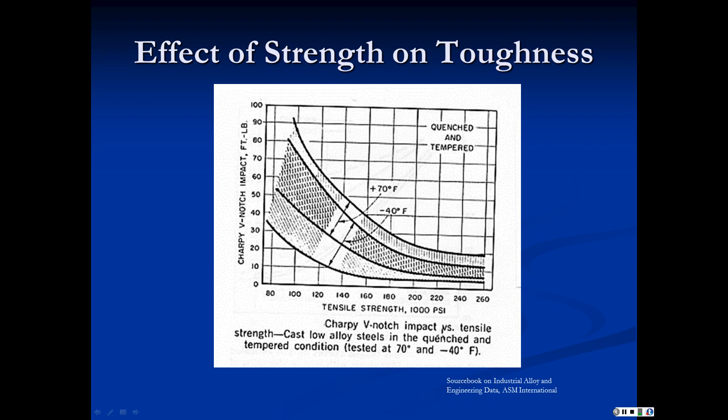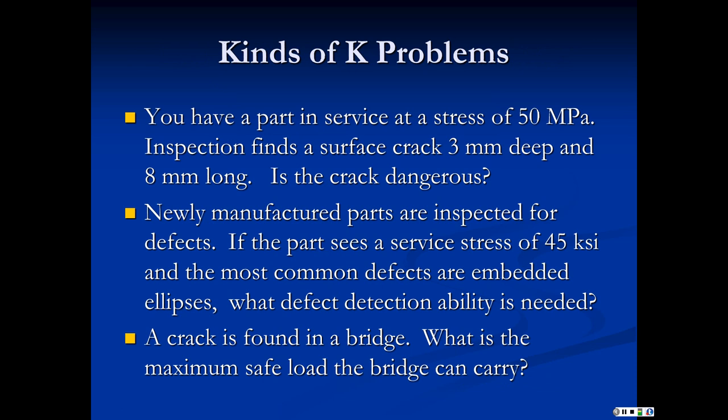As you raise the strength of materials, you dramatically reduce their toughness, and toughness is your insurance against unexpected problems. So you design to the required strength, no more, and you keep it just where you have to be to keep as much toughness in the structure as you can. It protects you against things you didn't know might happen.